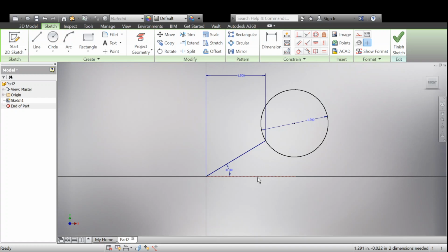So we're going to talk about dimensions and how things are functions of each other, and that will happen a lot with this. For example, if I created another line, watch this, ready? I'm going to arbitrarily make that line not parallel to the line I started with earlier. But if I look up here at the top, I see all these features called constrain, which allow me to constrain features. I can make two lines have to be parallel to each other by choosing this parallel feature. If I click it, choose the first line, then the second, the second line automatically becomes parallel to the first one.